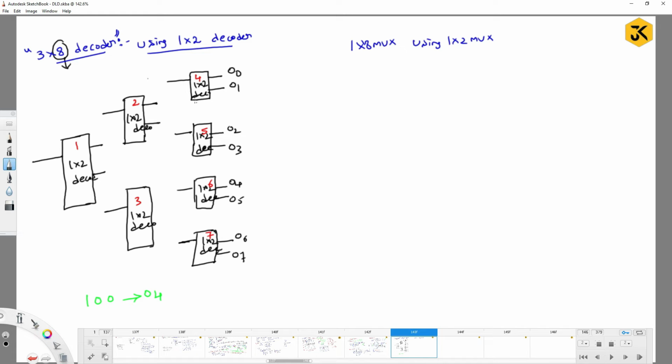Basically, guys, observe that for every decoder or any kind of circuit, there will be one more line called the enable line. What is the use of the enable line? It is meant for switching the circuit on or off. So here I am using the enabler to control the respective circuit. I am not passing any input, I am just passing the voltage. That's why I am simply activating it. So I can make the connection like this.